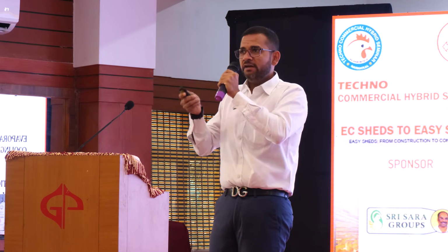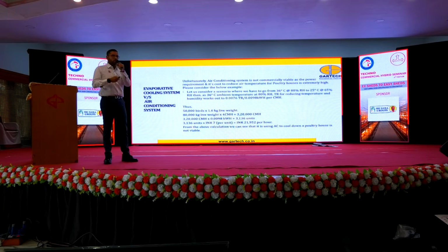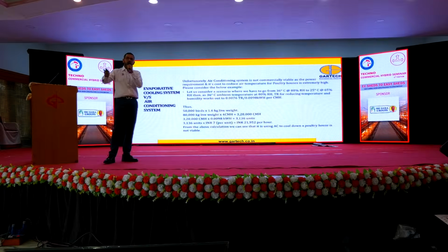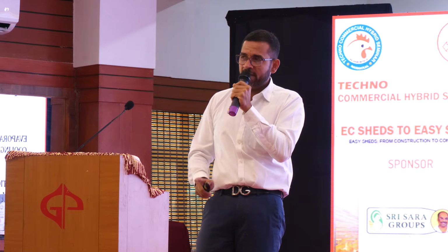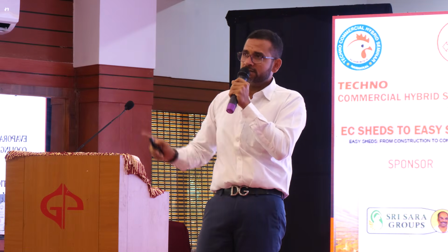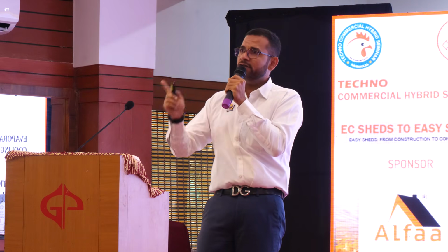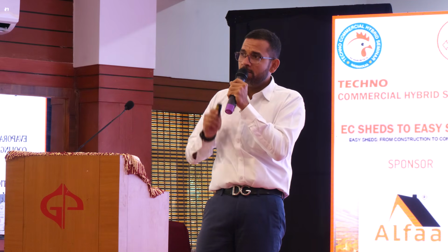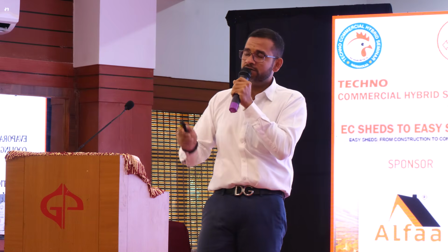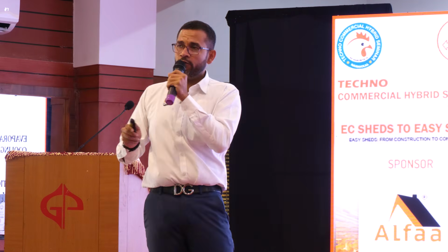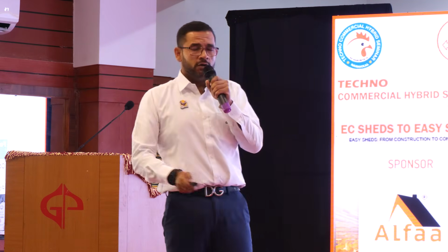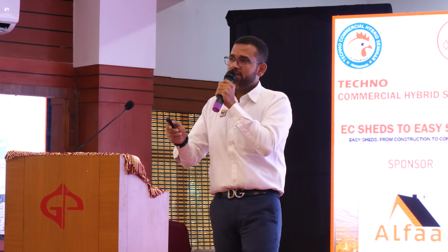So we are left with evaporative cooling and no other option, but again, a well-designed house, a well-insulated house, not just cooling pads and fans, but a complete system. Turbo tunnel ventilation is the key, where air exchange without increasing the velocity inside the house is the way to go if you want to achieve good results in an EC house.